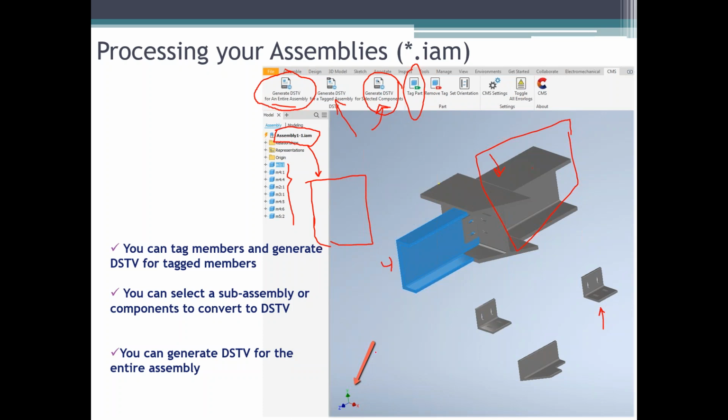And then to minimize issues, again, remember we are talking about this set orientation stuff. So if you have a different orientation, and they are not necessarily following this generic standard, which is your front face on the XY plane, and the extrude, the plus Z, is coming out of your screen.